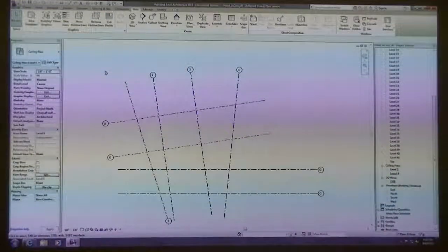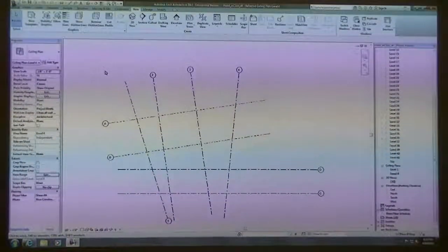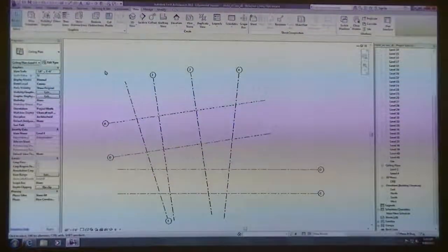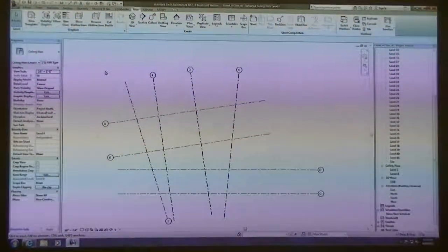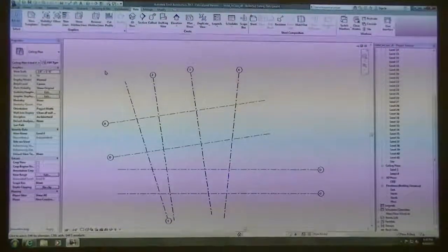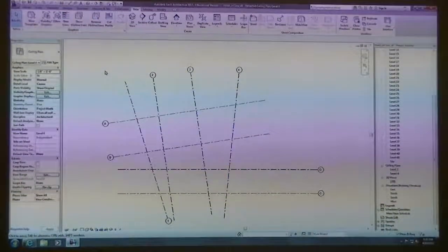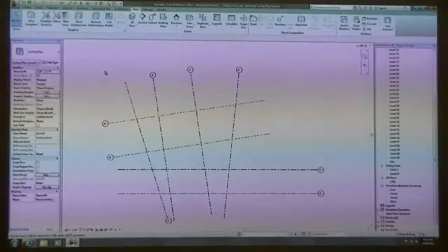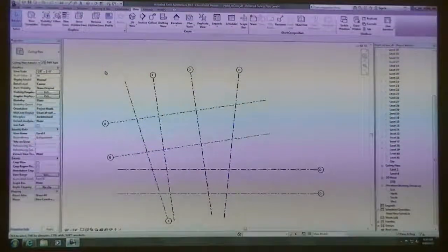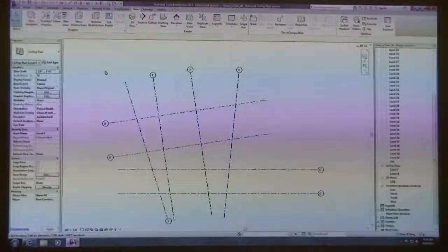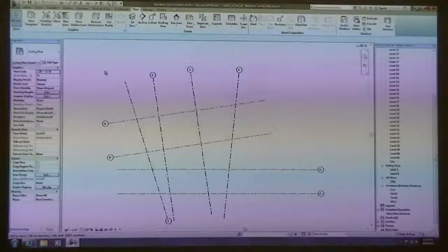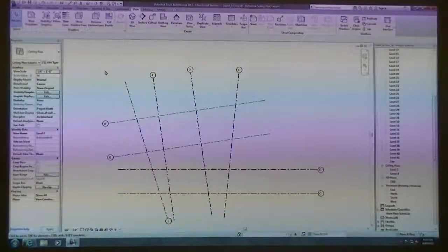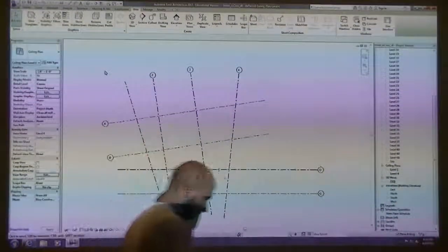The reason is that whenever you bring in a SketchUp file or an AutoCAD file, Revit doesn't recognize it as solid geometry. It doesn't understand that if you cut a section through that model, you're able to cut through and see hollow information. So it's always showing you an elevation view or a plan view of that model. You can see here I'm in my hotel project, in the ceiling plan on level 4, and I can't see anything except these grids.